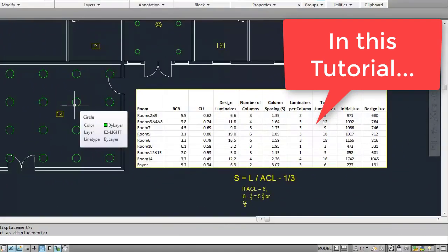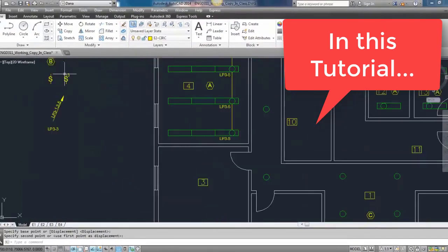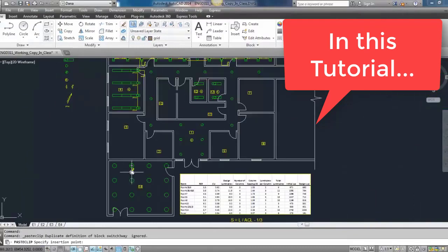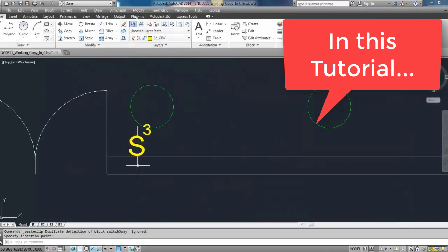Your 250 watt luminaires. And because they have such a high wattage, you're going to need 2 circuits for this room. And so you're going to have 2 sets of 3-way switches in this room as well. So let me just show you what that's going to look like here. So right near the opening, you'll have to select the side for the 3-way switches. I think I'm going to use this side here because it just kind of makes